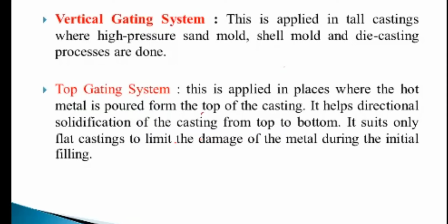What is the advantage? Why do we need it? Metal is entering the mold cavity from the top, that's why it is called the top gating system. It helps directional solidification, which is very useful for the casting.